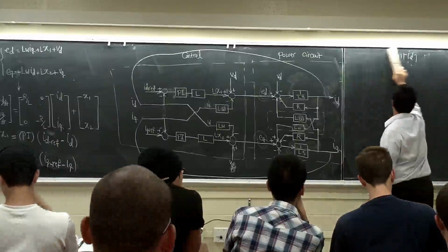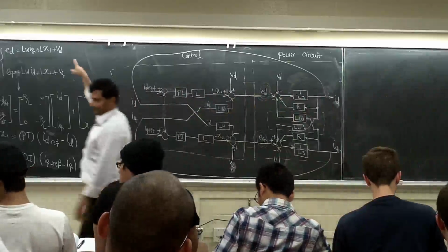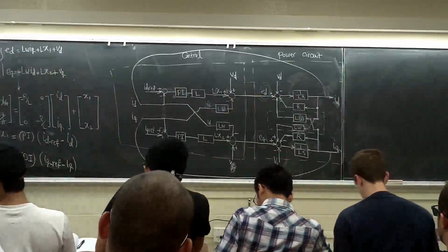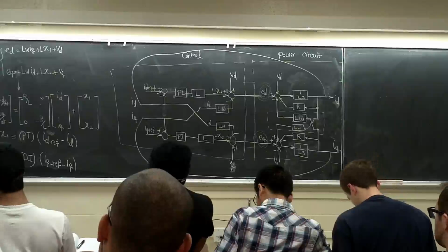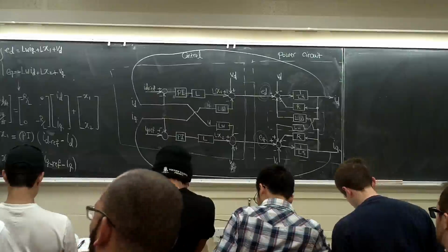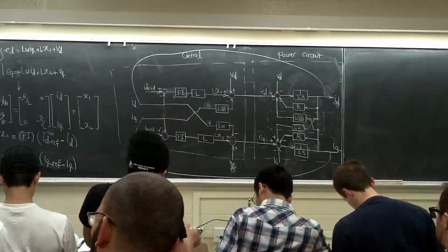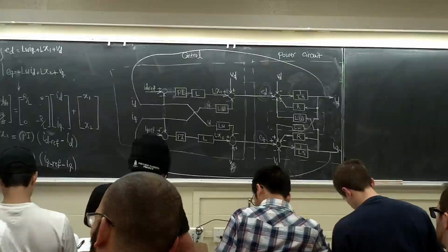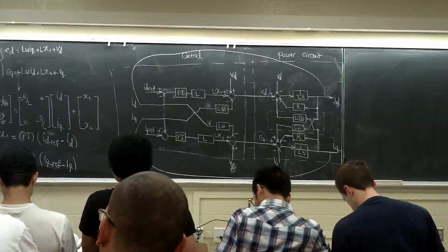Professor? Yeah. So we derive the control pattern based on the equation we use over here. Yeah. In this case, we use an integrator at the end. But if I rearrange this equation, I can use a differentiator as well. Yeah. But you need to calculate how you're going to size those. Let's say we move everything to the left, just isolate ID, and then we get all the terms from there. In this case, we use a differentiator. But we try to avoid differentiators in the control system, since it's going to make the system very prone to instability.